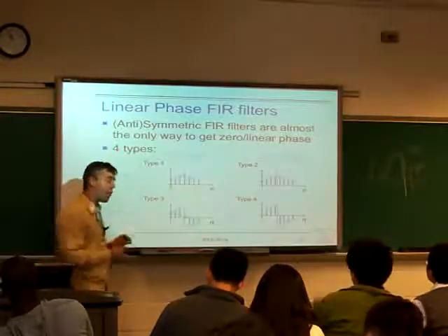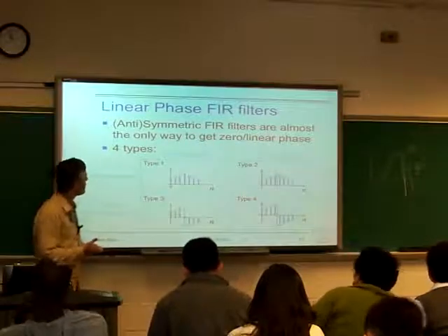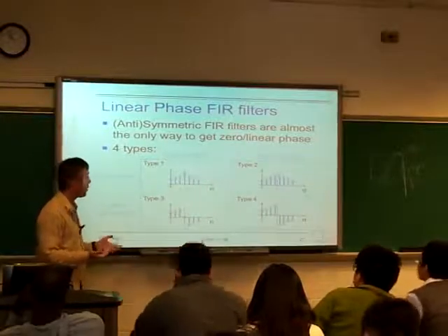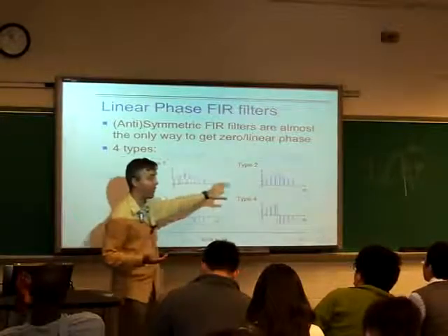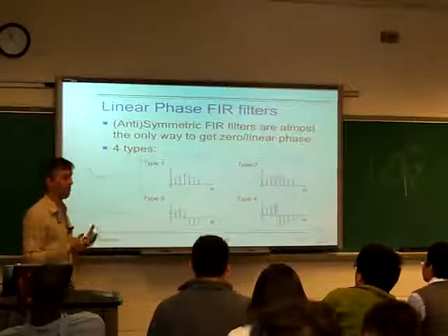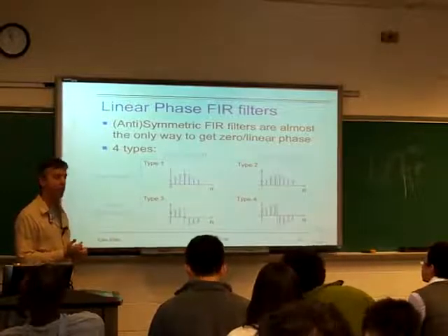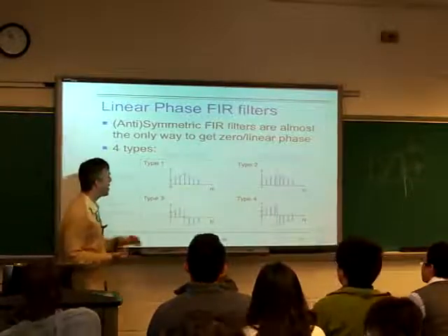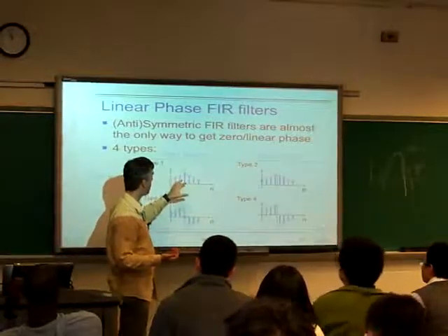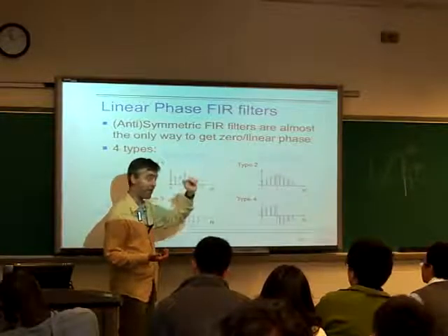OK, so there's a second way to get linear phase, or constant delay, filters. And that's to use FIR filters with a constrained shape. Basically, symmetric FIR filters is the trick here. And this was a novelty when discrete-time processing was first introduced, because suddenly you could specify your impulse response point by point, just by having a delay line and a set of gains coming off it.